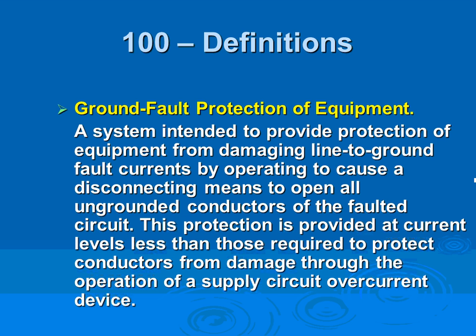And 277/480, that's the most powerful voltage that we use. It pushes a lot of energy. It burns a lot of equipment. At 1,000 amp or higher, you're required to provide a separate device or a function inside the existing device that you have. So it could be a function in the power circuit breaker or a separate device in addition to the circuit breaker that only looks at the ground fault and only trips or alarms at the ground fault situation. Because it becomes so high and so important, guys, that you need to look at it separately.